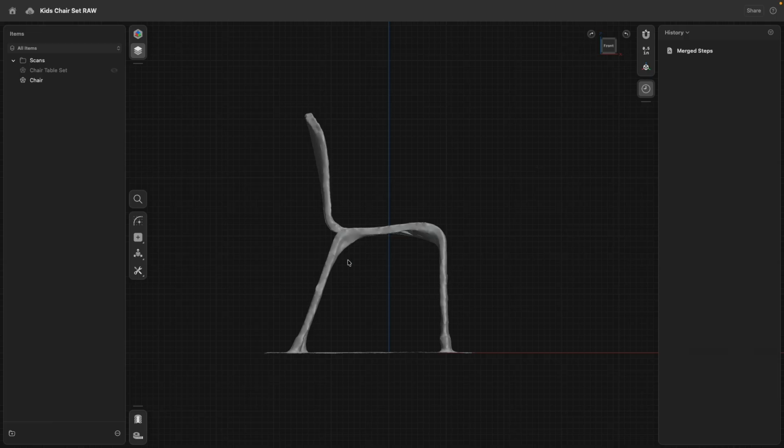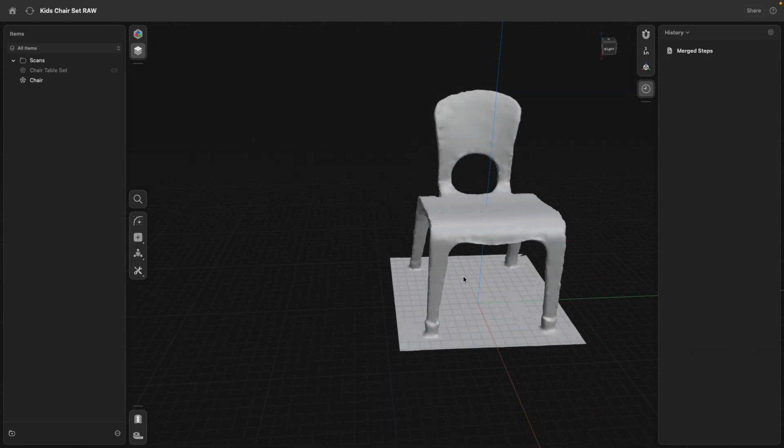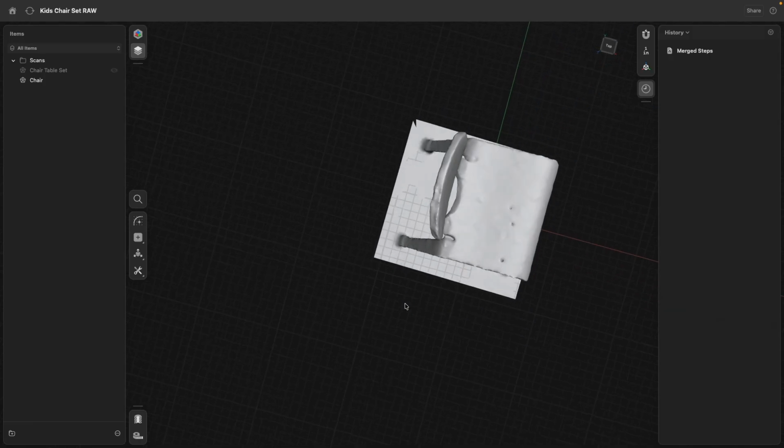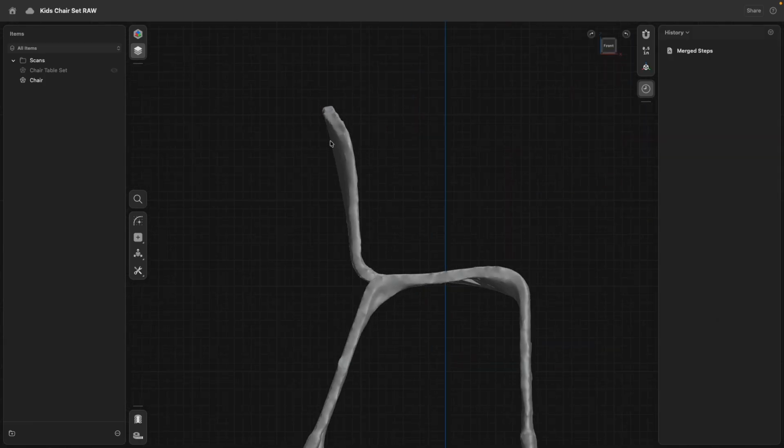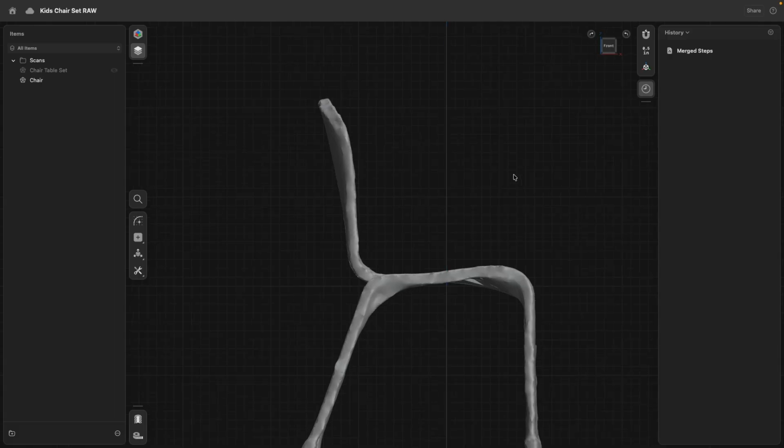So from the side, we can see that the legs and the seating surface are kind of like, we can draw this profile and extrude it and then cut these openings. Easy peasy. The backrest is a little bit more detailed because we can see here at the midpoint, it rotates more to the left side, and to the outside, you see this edge is more moved to the right side.